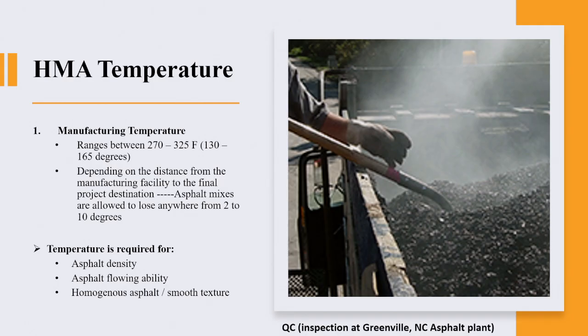Let's put it this way. If you have your truck mixer filled more than 1/3 to 1/2, the rotation is not going to be efficient in maintaining the workability. So it hardens inside the truck. That's one of the major concerns of the contractors who do the work in RCC. When they do the pricing for the project, that's one of the reasons the cost goes up.